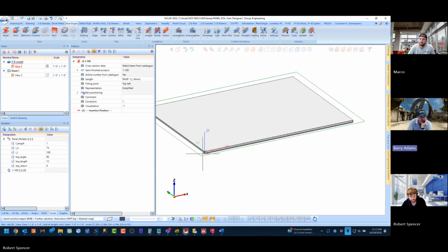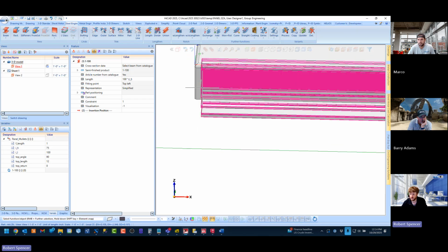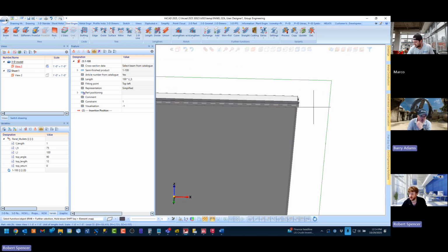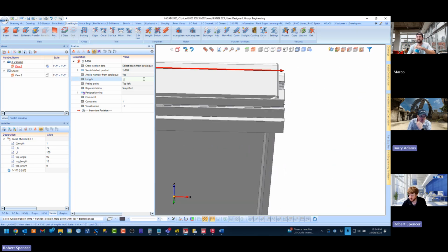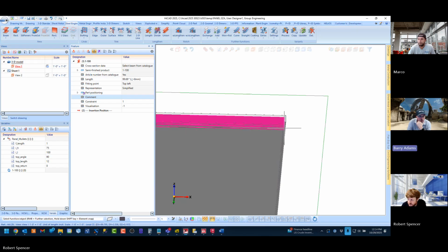didn't you already minus 4 on this side when you did the offset? Yeah, but to be protruding 4 millimeters through. You're already adjusted. So you're already 4 in here, and that has to do with the offset. So here, if you say minus 4, referencing IL, it's only half as much as you need. It's because of your reference IL. Yep. Now, you might want more than 4, but at least you see how the concept is. If you need more clearance, that's fine. Put it in there. Right.